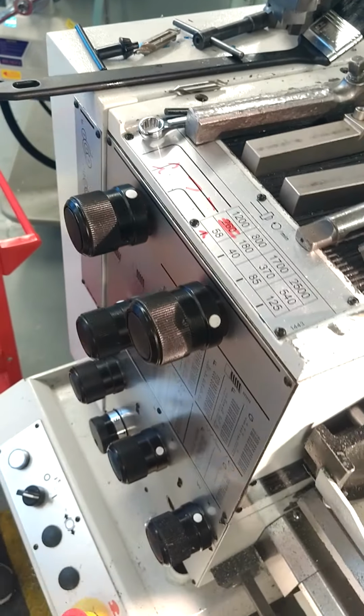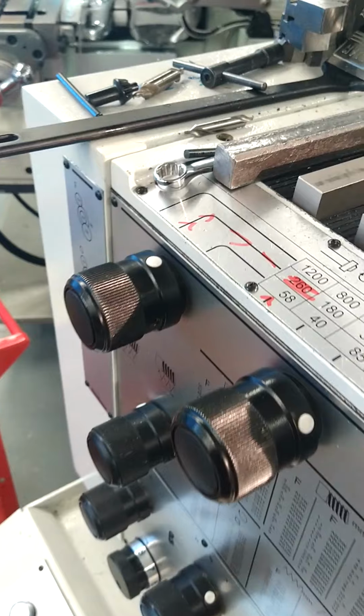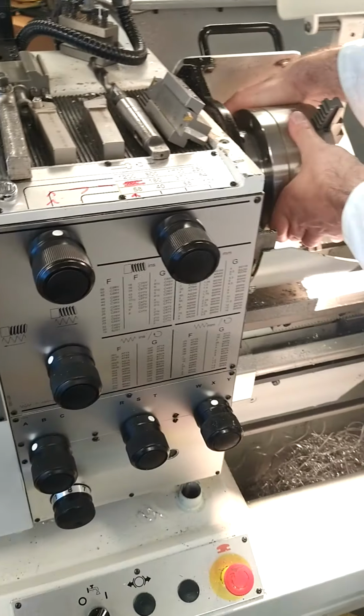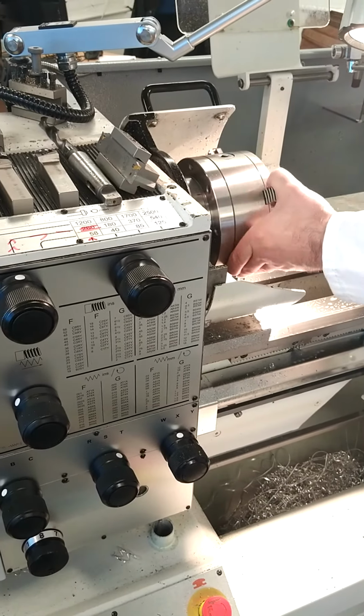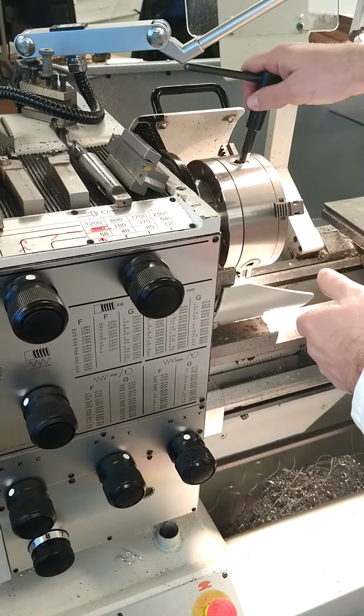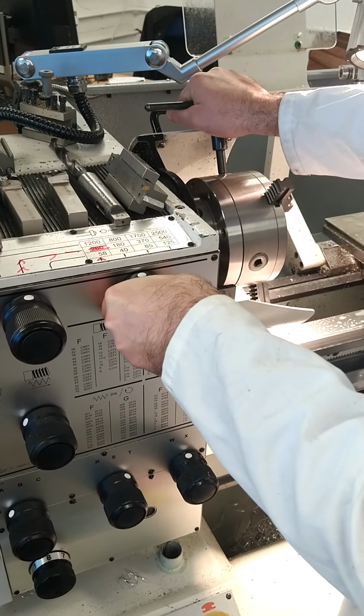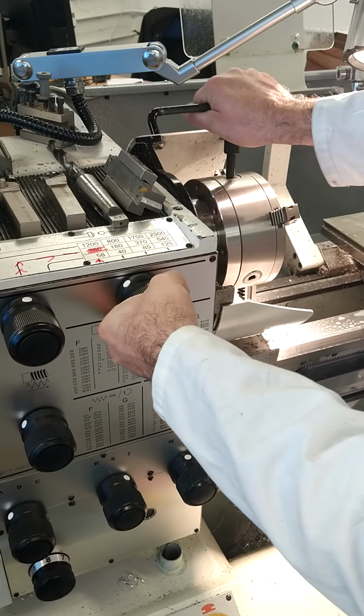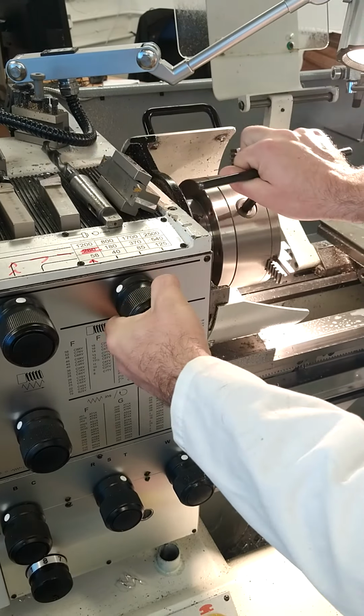So to do that, if you find it difficult to rotate the chuck at that low speed, you can use your chuck key to help you get some leverage to help your rotation. So you press in and rotate, and it's a gearbox. So we always set the speed on the lathe when the machine is stationary. So we rotate around and we're in position. So now we've selected the 260 RPM. So it's in gear. I can feel it in gear there now.